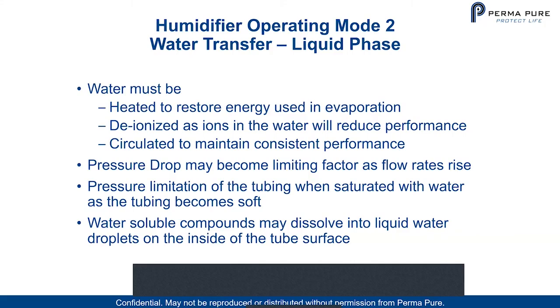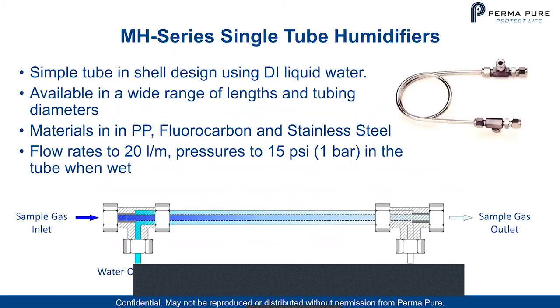The other limitation is that there's a pressure limitation of the tubing when saturated with water, as the tubing becomes soft. And water-soluble compounds may dissolve into liquid water droplets on the inside of the tube surface. And that was an important concept, because what happens is that you have water droplets on the outside of the tube where your gas is.